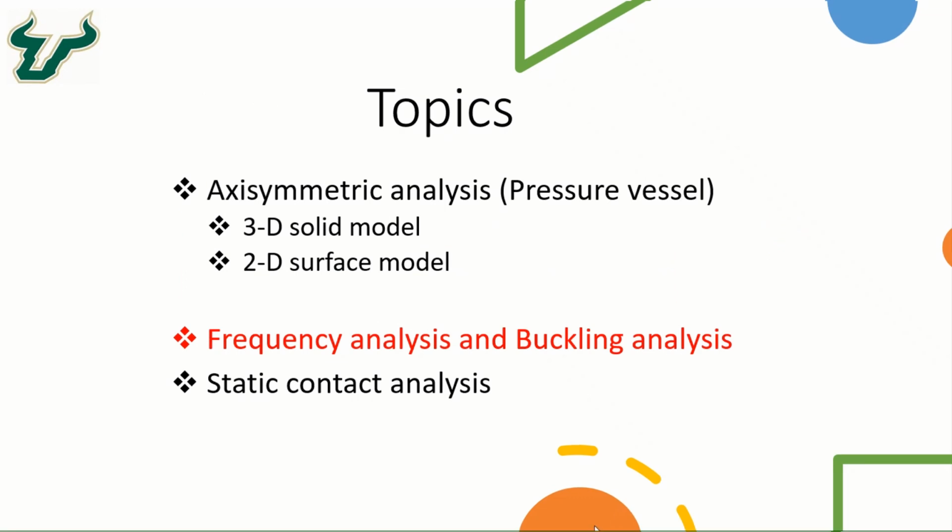In this lesson, we will take a look at the frequency analysis and the buckling analysis. What we're going to do is just consider a very simple part and understand how to set up the problem for the frequency and the buckling analysis. We are also going to do the theoretical verification from the equation based on the Euler's column formula for the buckling analysis, and also the equation for the fixed free condition to calculate the fundamental natural frequency for a